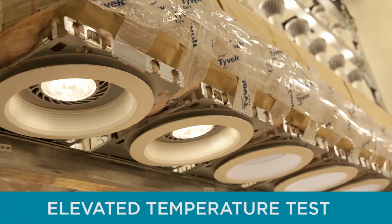Finally, let's define elevated temperature testing. Elevated temperature testing is a type of testing that manufacturers must do to ensure that their products do not suffer from early failure when placed in luminaires where elevated operating temperatures are common. For example, these conditions are often found in enclosed or recessed luminaires, which can lack good air circulation and ventilation.